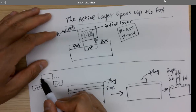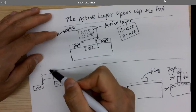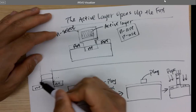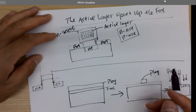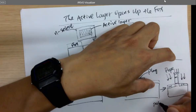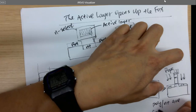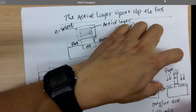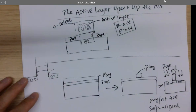But if you have a gate on the top first, then you dope it, see? And this will become a perfect boundary between the channel and the diffusion. So through this process, the poly and N plus are self-aligned.